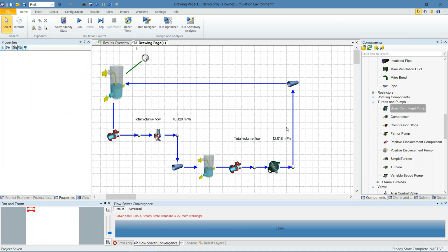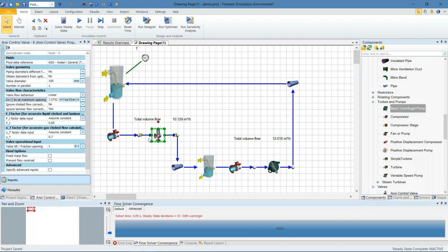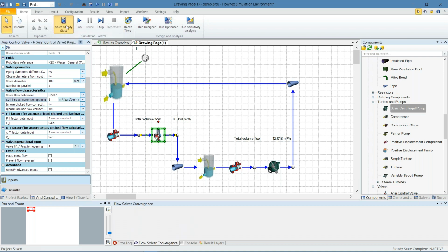Under its normal conditions, we then see our volumetric flow being higher. We also know that our valve over here is going to be completely limited. I started designing this valve with the valve completely open. So when this valve is fully open, we get a maximum flow of about 10 cubic meters an hour. Perhaps the level in the tank is too high and we need the tank to drain to regulate this level. We'd need to specify a higher CV. So instead of 7.2, perhaps we choose 8 as a CV.